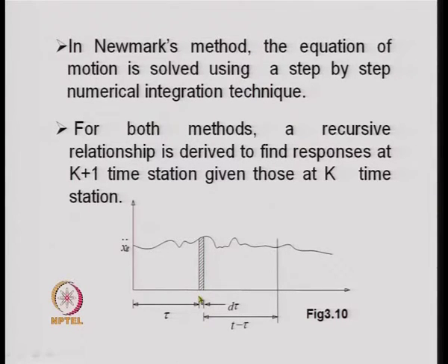From here we start counting the time. So, at 0 time, we consider the displacement and the velocity, and substitute them into the equation that provides the response at any instant of time t for a damped free oscillating single degree of freedom system.